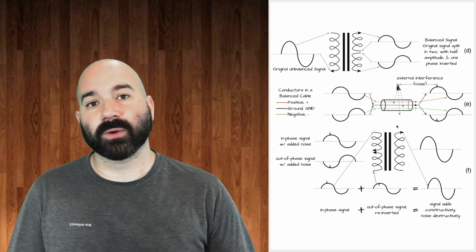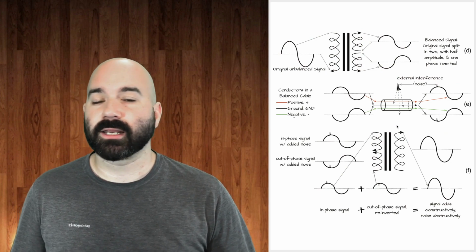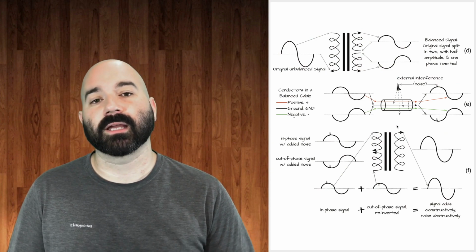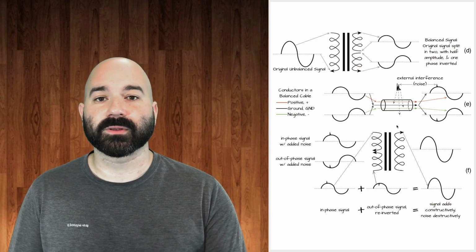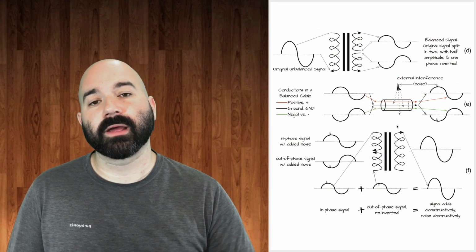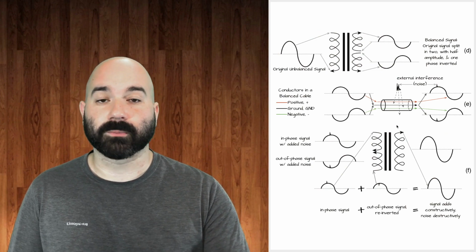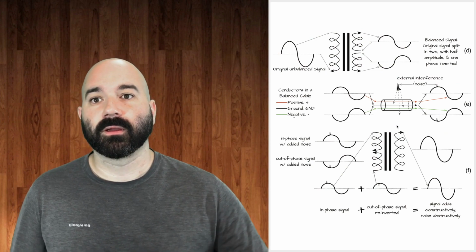So again, to fix the ground loop issue, you just simply lift the ground so that it's not connected between the two devices. And again, you do that with either a built-in button on either device or a DI box, but never do it by disconnecting the ground of the power outlet or the power cable to the outlet.